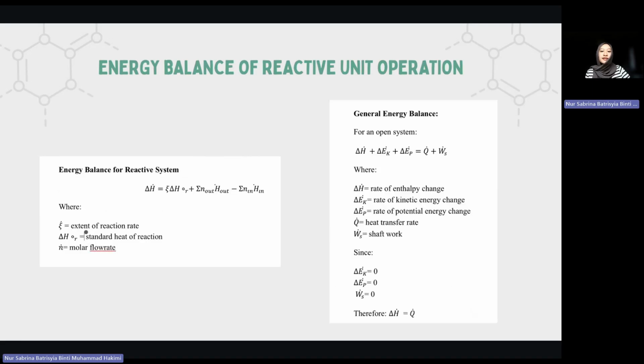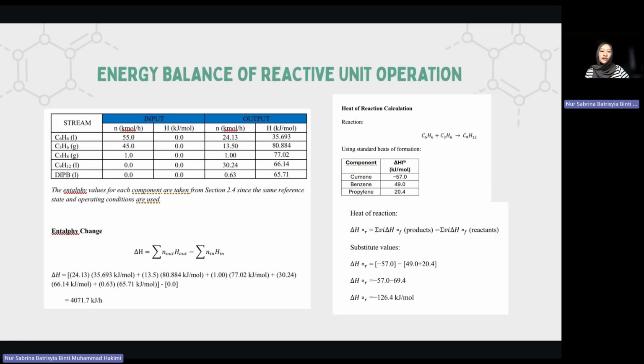The energy balance relates the enthalpy of the inlet and outlet streams together with the heat of reaction. So we use this formula here for the general energy balance, and then the reference state is set the same as the non-reactive unit operation, which is 25 degrees Celsius and 1 atm. So the enthalpy values calculated earlier in non-reactive can be used consistently.